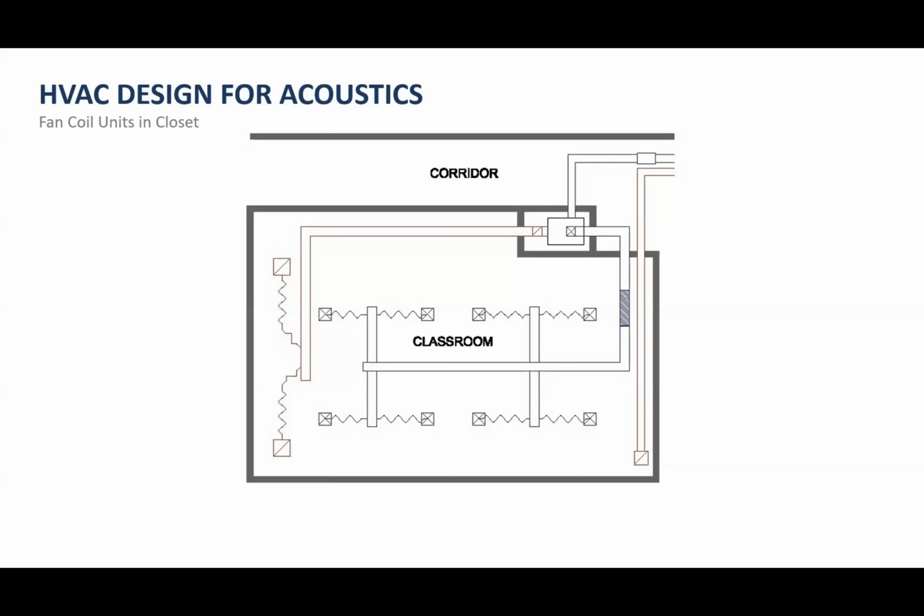Acoustical flexible duct is typically recommended at about 6 to 8 feet before the diffuser. So again, this gives that last little spot where you can have some absorption. Most ductwork otherwise isn't lined, while it still does reduce sound and can be lined in some cases too. Acoustical flexible duct is more commonly seen, and right there just before the diffusers it helps to reduce the sound level a bit more.